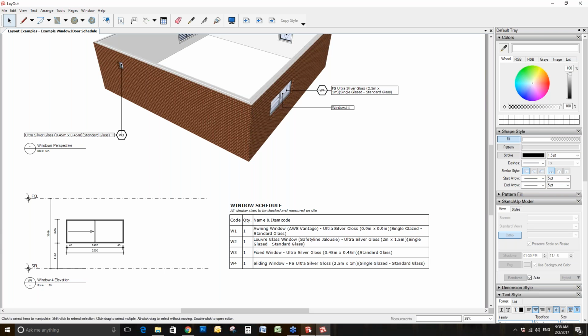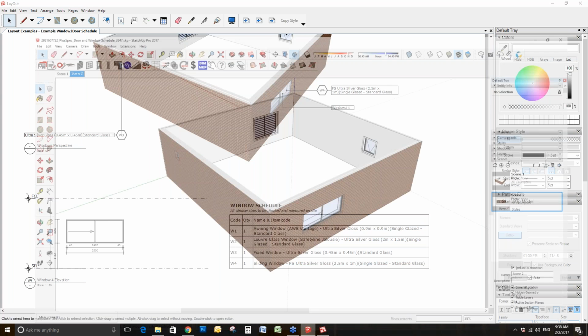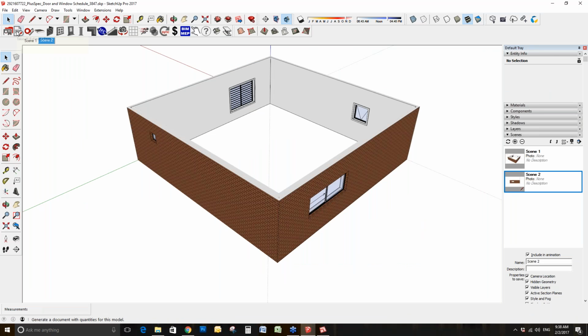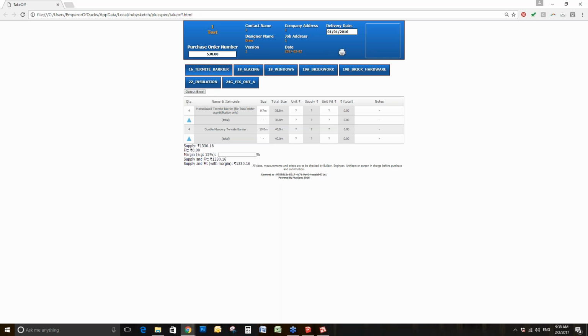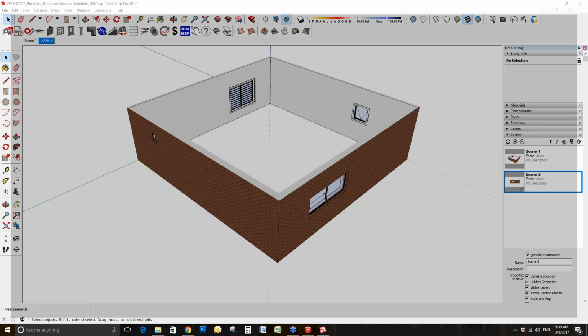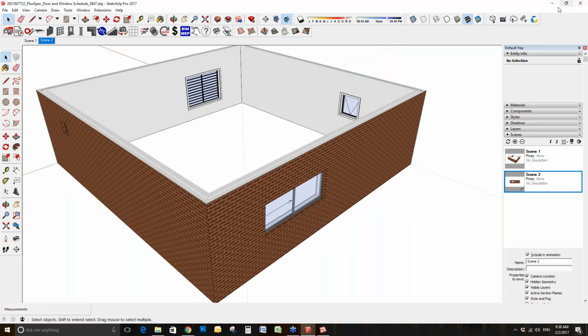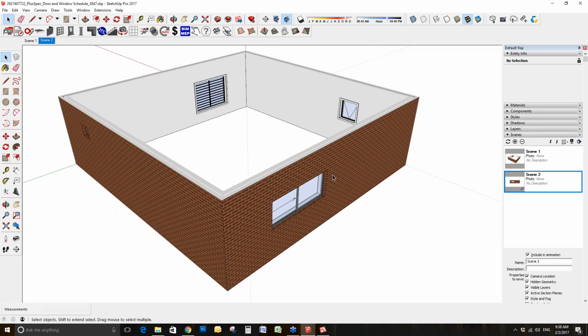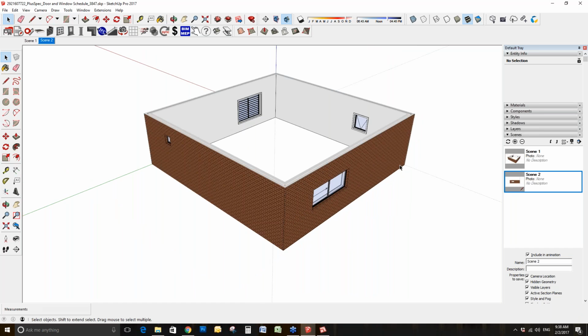it produces the schedule. So again, if I go back into here and I click on the takeoff, it's generated my takeoff. If I click onto my Windows tab, it's brought in all of the information about those windows or doors. That means if I output this to Excel, which I've already done, I can then manipulate my Excel document even further. I can start to capture exacts, numbers, putting any other information in there, whatever I want to do. Then you're saving it as a CSV file.